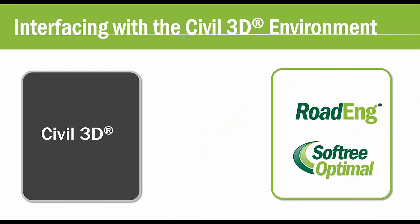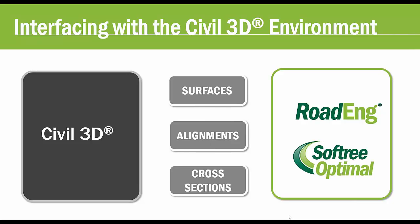So the key principles that Craig's going to cover today in this interface discussion really are the 3 different types of information that we use to communicate between Civil 3D and our programs, RoadEng Softree Optimal. That includes surfaces, alignments, and cross-sections. For surfaces, we're talking about the original ground and the subsurfaces. For alignments, we're talking about both the horizontal and vertical alignments for our corridor center line.